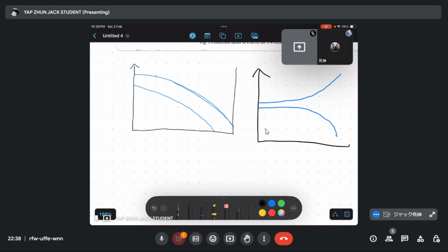If me, okay, this is counter current, and this is parallel flow, which means they will enter at the same place. Then one will increase its temperature, and one will decrease its temperature. From this, we know this one is decreasing its temperature and this one is increasing its temperature. So we already know these things. This will be the cold input, actually. I just write C in for cold input. Why do I say it is cold input? Because the temperature is increasing toward here. Okay, so we already know this is C in, so this will be C out. Okay, this will be hot in. Hot in, that temperature is going down, so this is hot out.